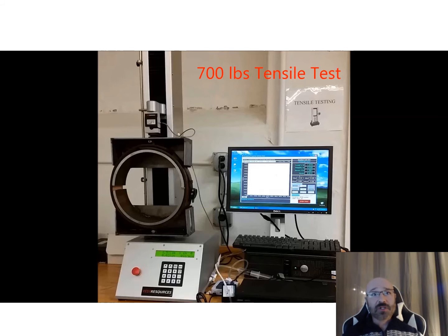But I was really more concerned about what is the maximum amount of pressure that a lifter is going to do when they crank that belt all the way tight and they brace and push out with their core strength. What type of forces are we going to end up seeing translated into that ladder strap? So what I ended up doing was some realistic testing where I put pressure gauges in. You can see some of these pressure gauges down here, and I'll show some pictures later, were instrumented in people while they were lifting. Some strong lifters were deadlifting some heavy weights, squatting some heavy weights, where they were really bracing off their belts and had it cranked down tight, and seeing what the realistic pressures were.